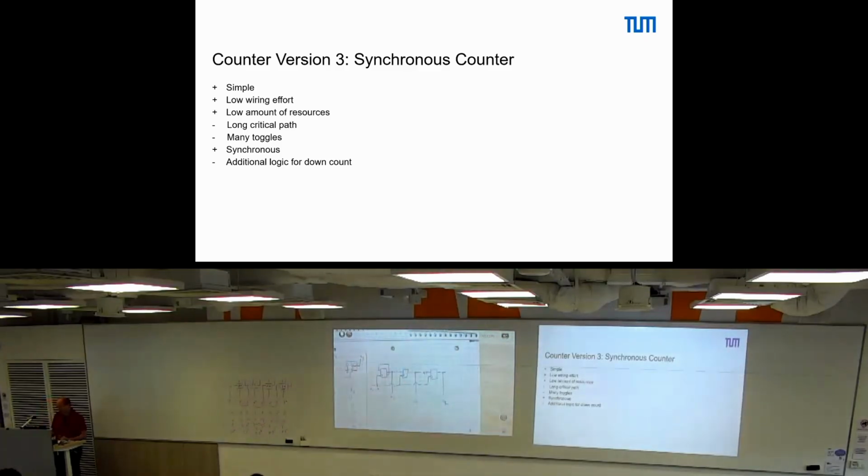Now, if we want to derive the input for the next bit at some specific point, we need some logic. If you do this for 3 bits, the first toggle should cause 001, that we implement here with this feedback. The next toggle should cause 010. This here is already there. This here takes over the value from here, so that's also correct. And then we need to go for 011. There's something wrong. And then for 100, something like this one here.